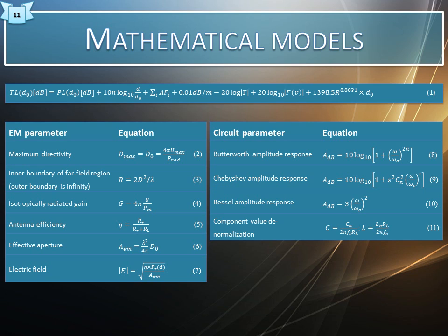The second set of equations are used to construct a dipole antenna to operate in the desired frequency range, and these parameters are verified through EM simulations in CST Microwave Studio. Mathematical derivations to estimate a first-order transfer function for low-pass filters are presented in the third table. These equations are used to determine the appropriate order of the filters that would enable the required attenuation, influencing the addition of noise to the circuit as well as the physical size.